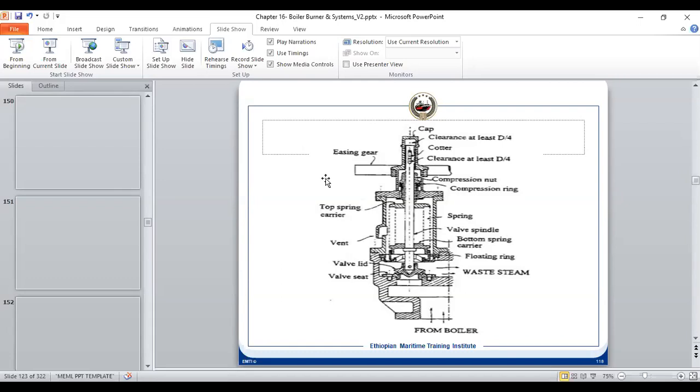Now for a boiler survey, obviously the vessel has to be taken out of service. We cannot do the boiler survey on a running vessel. Normally the boiler survey will be both on the exhaust boiler and the auxiliary or main boiler, as the case may be. So we time it along with the in-water survey, that is at 30 months or at 60 months with the dry docking, even though the boiler may not be due. But we still try to do it, because otherwise taking the ship out of service just to do a boiler survey is not economical at all.